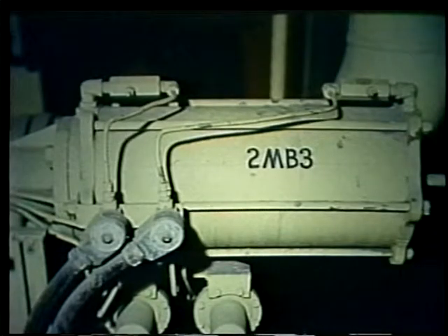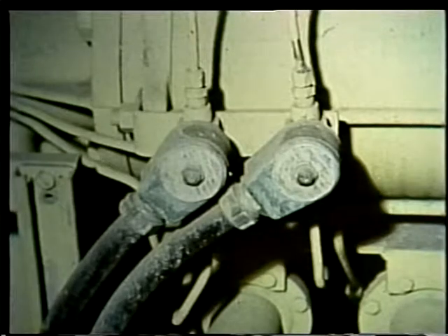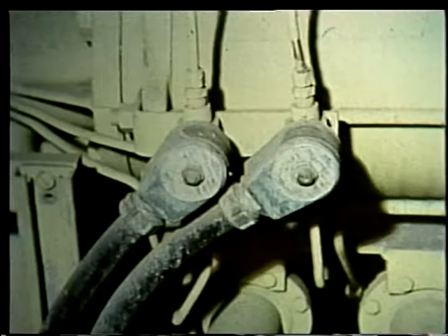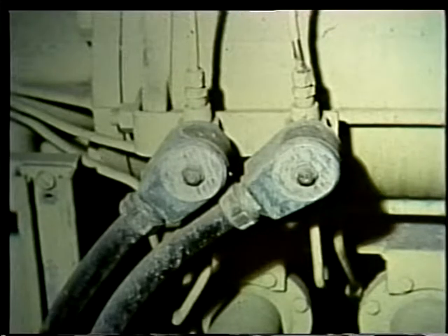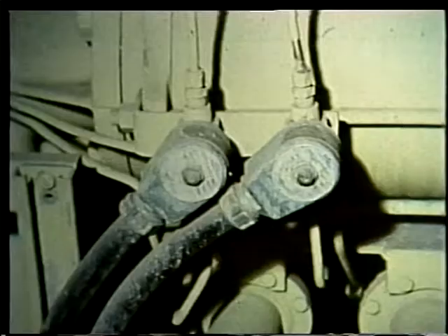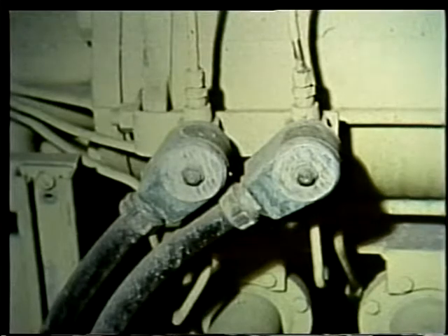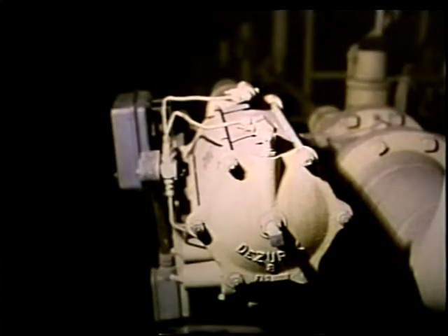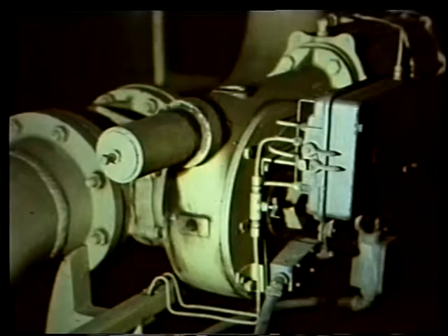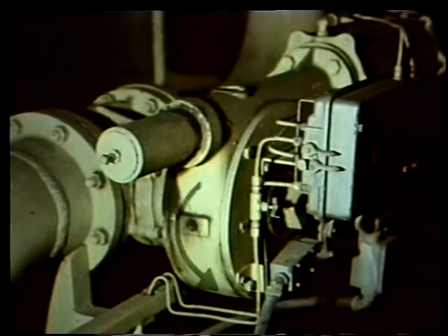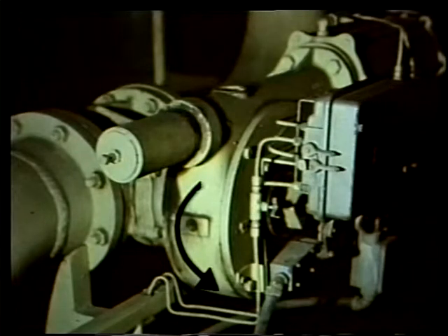Pneumatic and hydraulic motors operate in about the same way. The stem is rotated by a set of pistons that are activated by air or hydraulic oil. In this way, the stem is moved to open or close the valve. There are, however, some variations of the pneumatic and hydraulic operators. For example, they may be applied to a single piston, giving an in and out motion, or to a piston connected to rack and pinion, giving rotation.